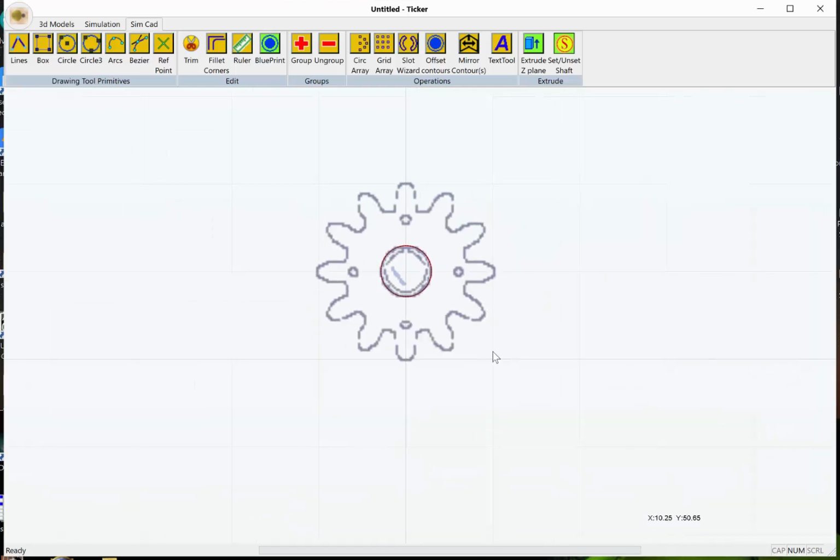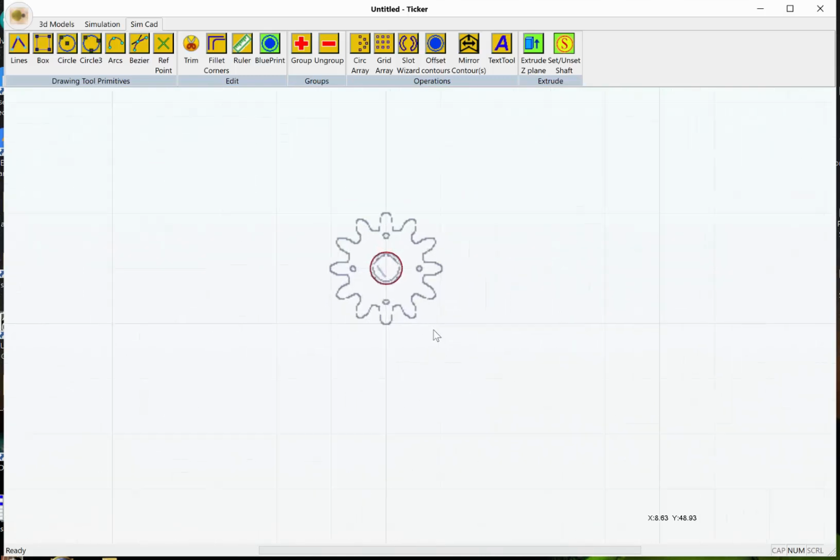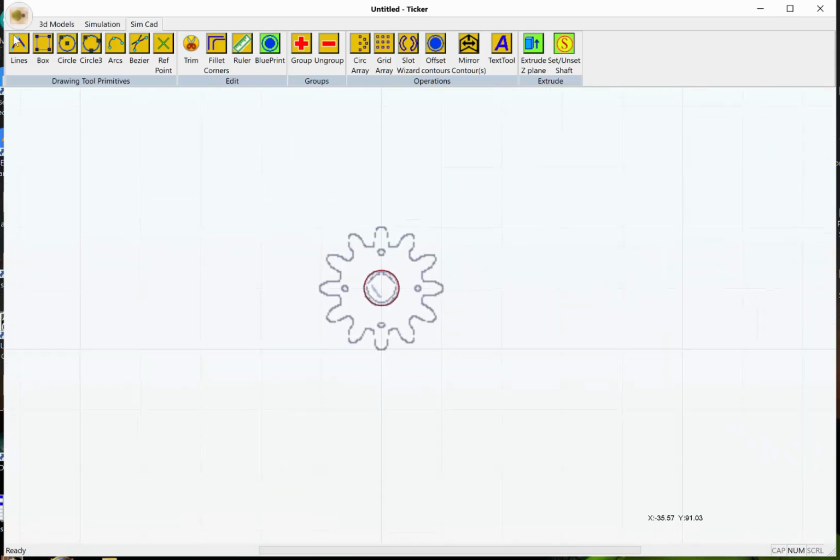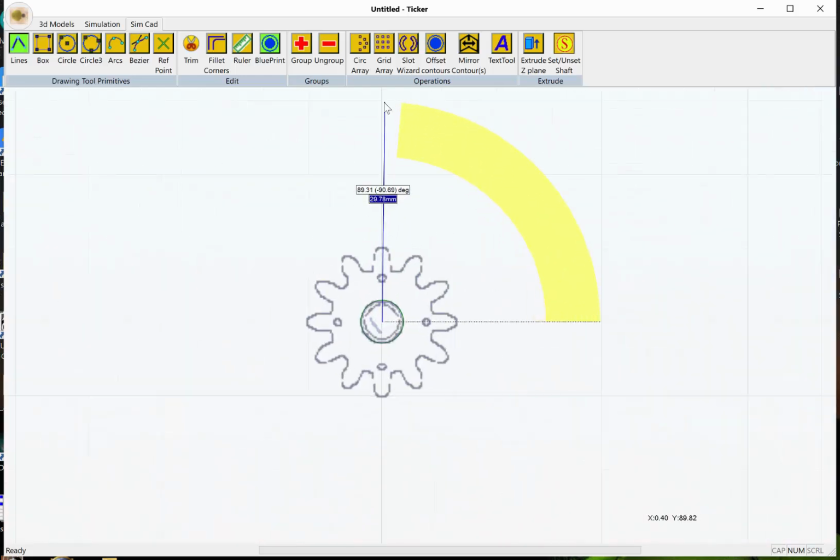All right, so let's draw a gravity ratchet on here. What I'll do is I'll go to my line drawing, and I'll go straight up from center. And the system will lock in important areas like center. You'll see it says CC on the screen on my mouse cursor. I don't know if your video will show that, but it actually says CC when you hover over a center. Let's draw a line, and it can be of arbitrary length, but let's take it up to here.